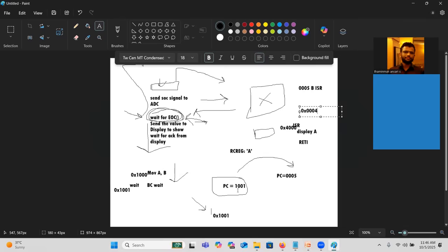From this memory address, you have to branch to a routine that validates whether the interrupt happened because of timer expiration or serial port receive or some other means. Based on that, it will execute a different piece of code. So this is another method. This one is a little bit slower than what I explained before. So there is a difference between these two. Is that clear to you now how these interrupt service routines and interrupts are working?